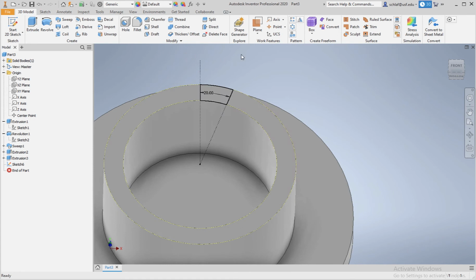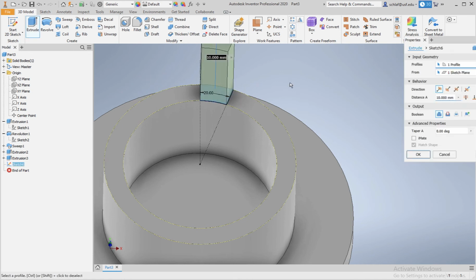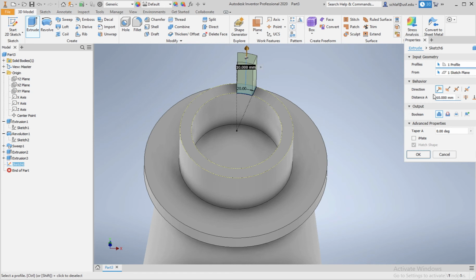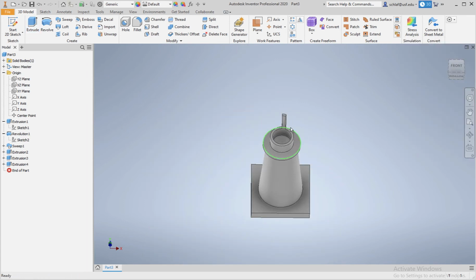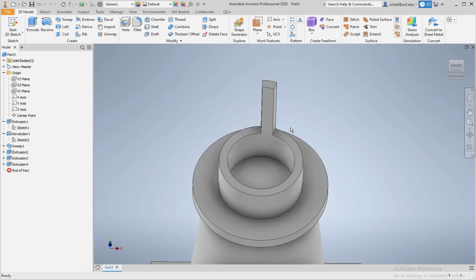This may not have been the most perfect way, like I just did it, but hey, it got it done. And now we can extrude this feature, and let's make this maybe 20 millimeters. It will be interesting to see how this prints, because when features get small, these printers can also get challenged a little bit. But anyway, here we see it now.